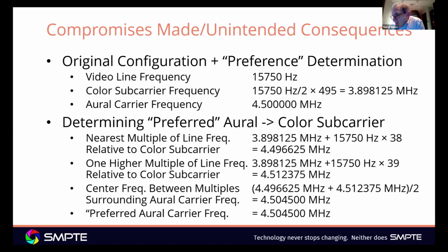And as a consequence, you'll have more interference in both directions from the color subcarrier information into the audio and from the audio into the color subcarrier. And in particular, there's a beat in the 900 kilohertz range that was particularly troublesome back in those days, and even into some of the period after color started to really take off. It took a while for what became a 912 kilohertz beat to be beaten into submission, if I can pun a little.